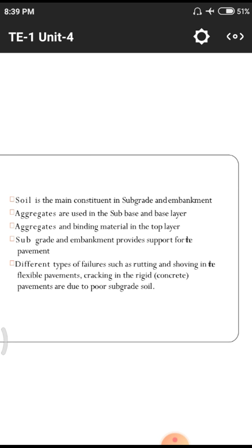If the vehicles are moving with a huge amount of speed, there may be sudden application of the brakes. Automatically, the force will have to dissipate on only a particular portion. At cross sections like junctions, we are observing these kinds of failures, rutting and shoving. Normally, at junction areas in highways or any other places near the villages, there may be some amount of road that will have to move.